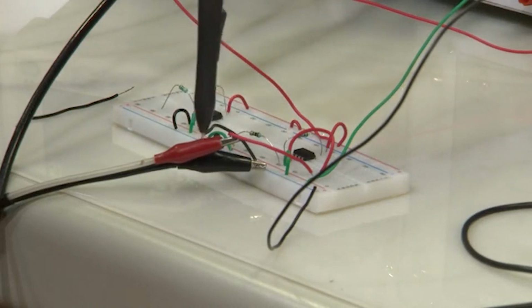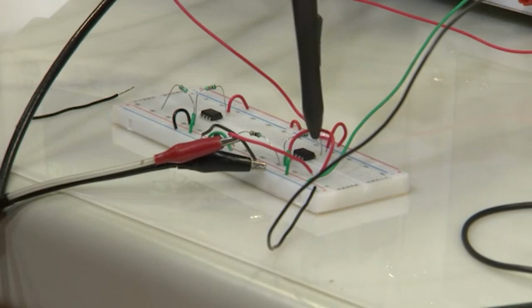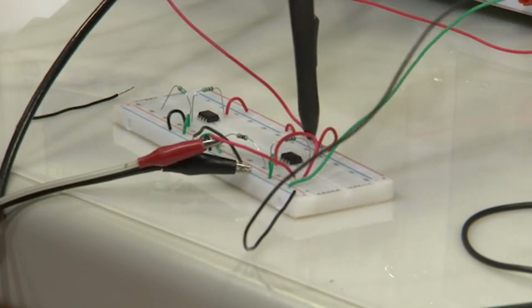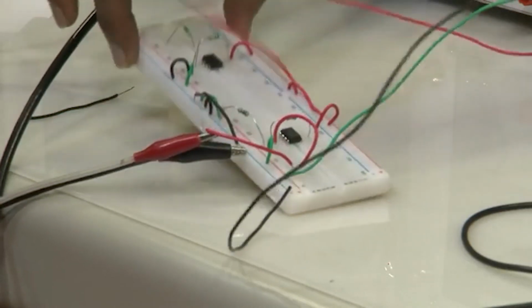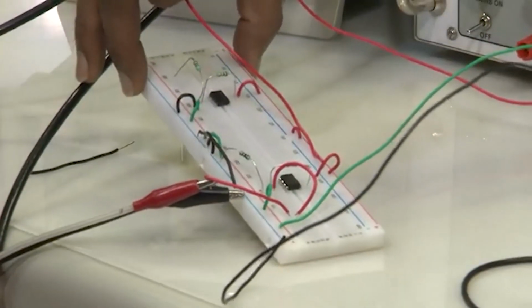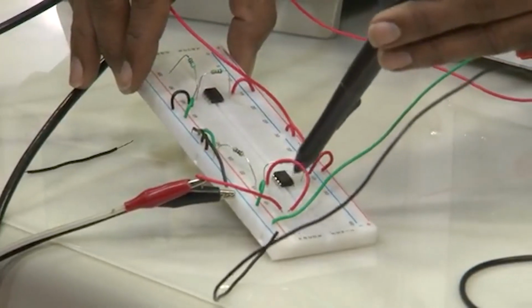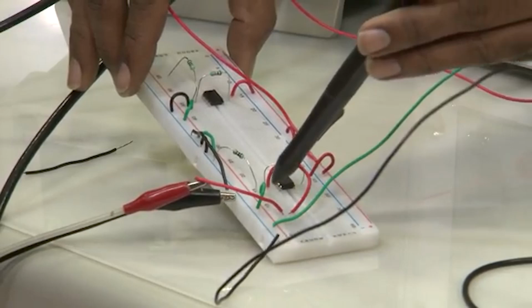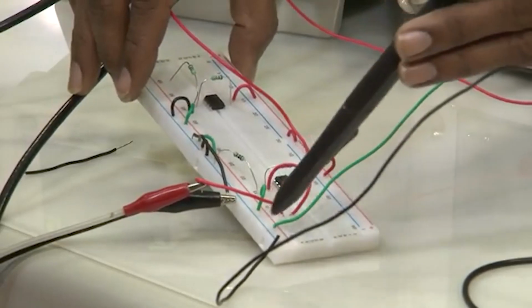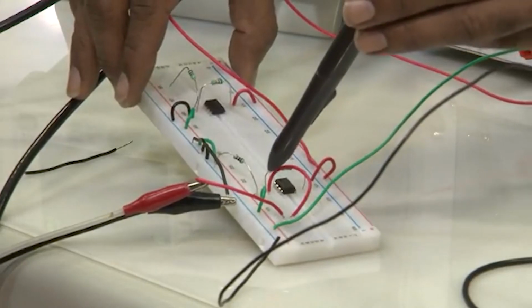Now we are applying the signal through this one to the non-inverting terminal of the operational amplifier. So, this wire is connected to the circuit, you see here, this wire is connected to the non-inverting terminal, and the input of the non-inverting terminal of this op amp is here, alright. So, understand from here that the frequency generator input goes to the non-inverting terminal.